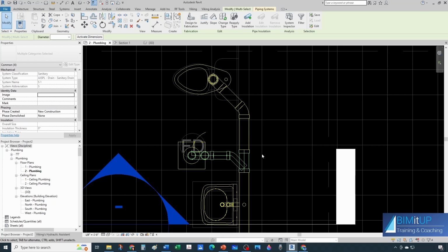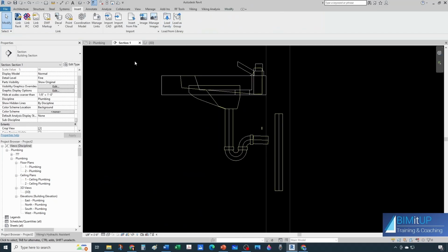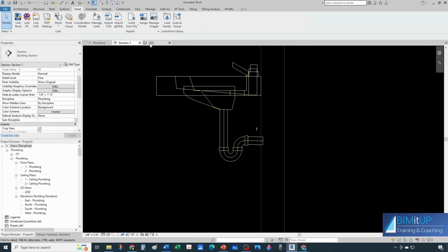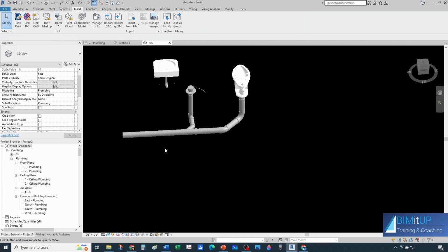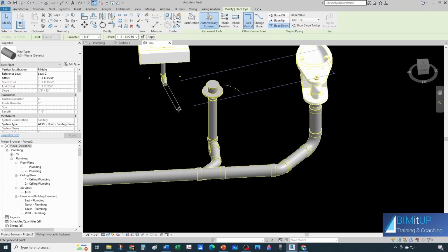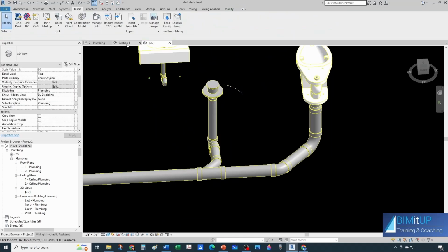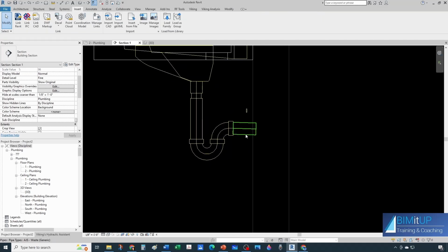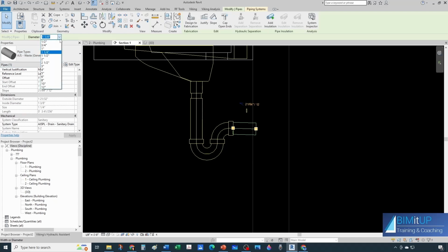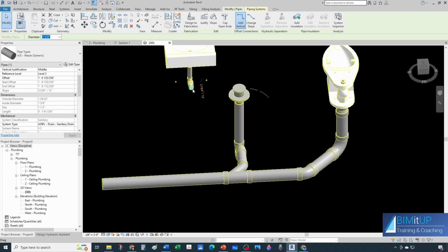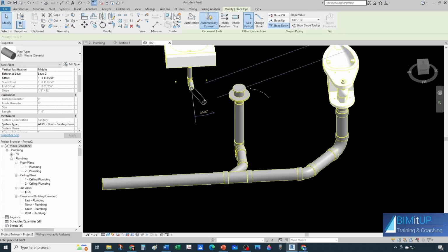We just coordinate with our architect so that the floor drain is a little bit lower, and then instead of having the stack here, what we do is we go to our 3D view, and then we turn our line. Instead of being 1 1/4, just so that you can have a longer run, you want to change this fixture arm to 1 1/2. And now you can go to your 3D view, and then right click, draw pipe.